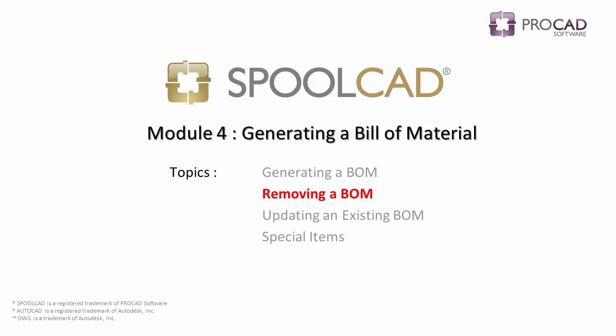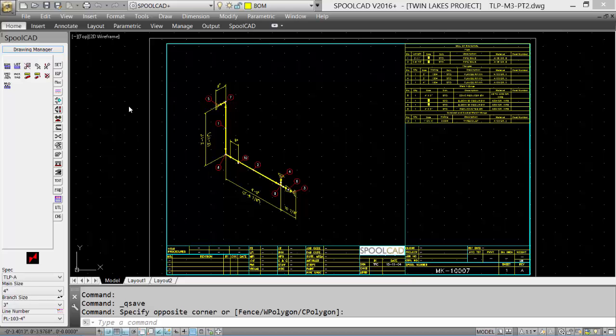Our next topic is removing a bill of materials. There are a lot of modifications to be done to a drawing. It is easier to remove the existing bill of material and item balloons, make the modifications, and then create a new bill of materials. Easy to do, simply click on the Remove Bill of Material tool.